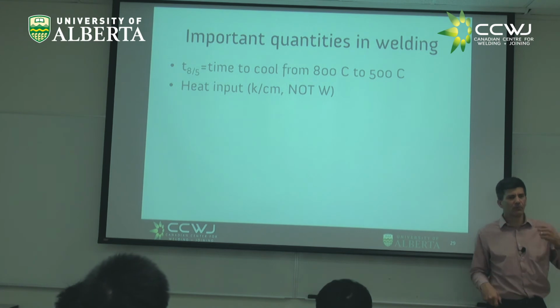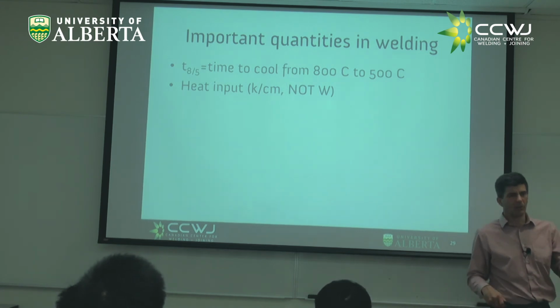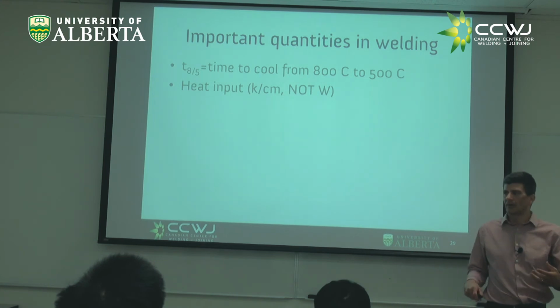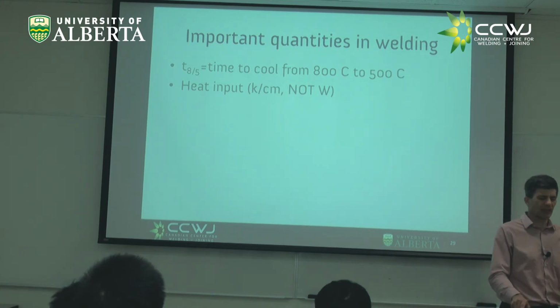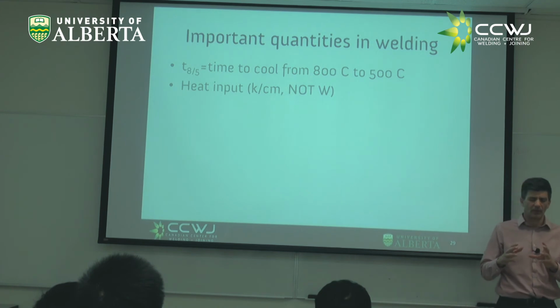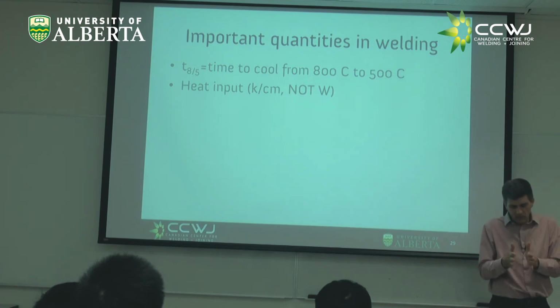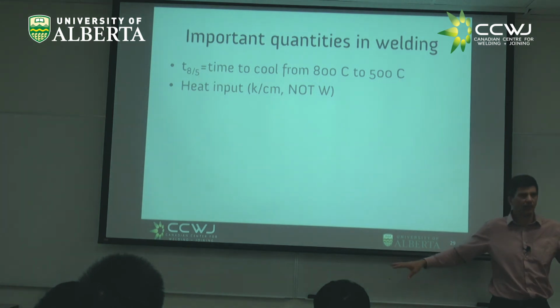So heat input matters. And if you remember, we said that as we weaved, we were going to have a slower cooling, right? So we get to see again these issues of heat input, in which putting a lot of heat in a short distance means a lot of time to cool down, right?